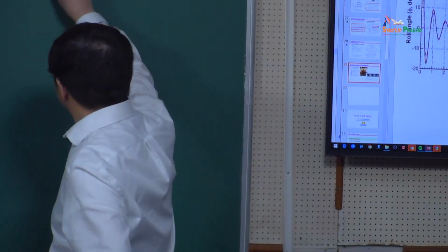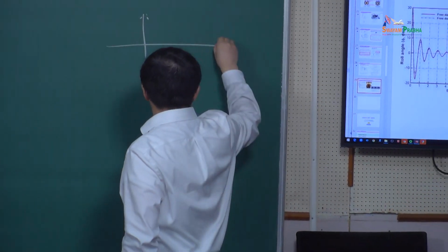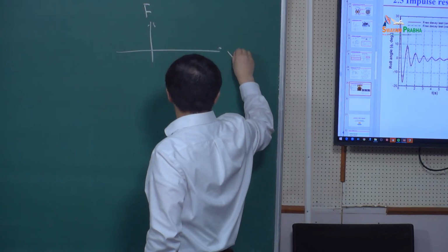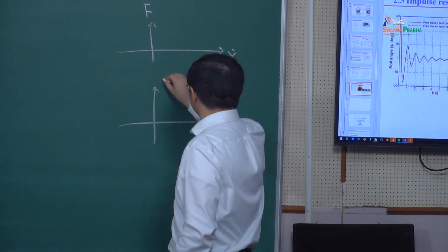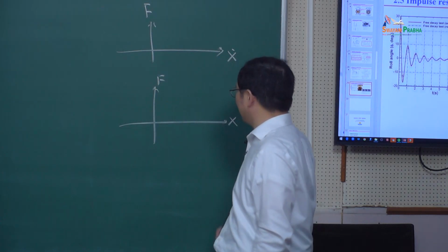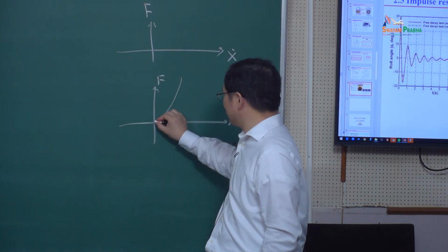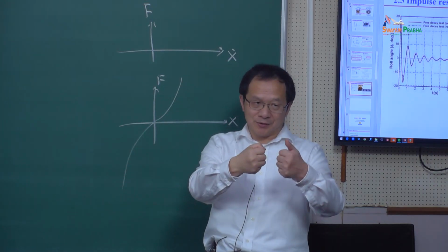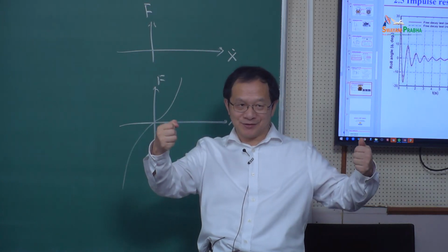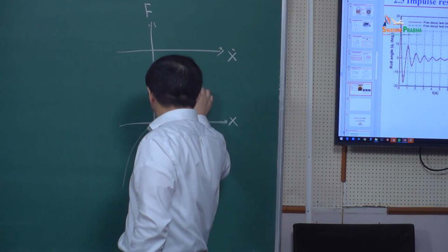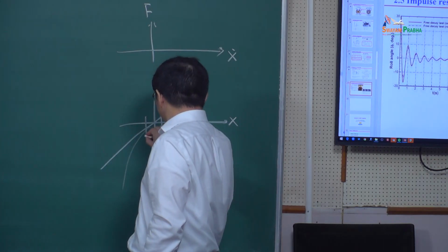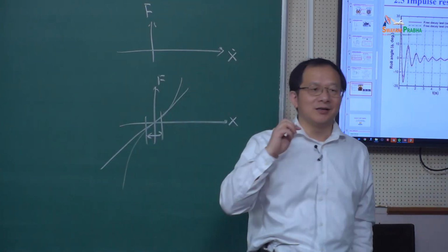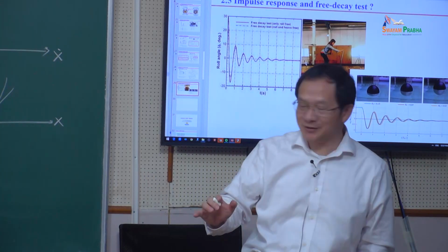Damping, you have force, you have velocity, right? And you have a spring also, you have force, you have displacement, right? And you can have different stiffness, like, right? Especially with rubber, you can pull that, it becomes stiffer and stiffer, right? And then normally when the vibration amplitude is not that large, linear is a good approximation, right?